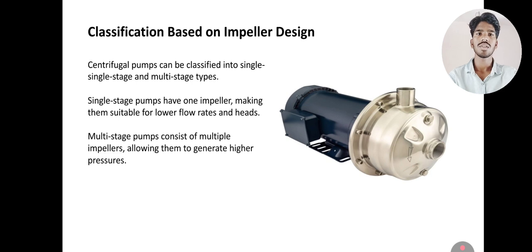Next, classification based on the impeller design. Centrifugal pumps are classified into single-stage and multi-stage types. A single-stage pump has one impeller, which makes it suitable for lower flow rates and high heads. And the multi-stage consists of multiple impellers, allowing them to generate high pressure.